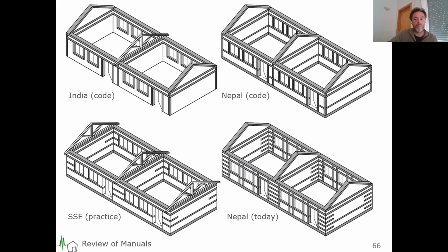So this is that first copy-paste issue that I've already shown. The second reason is panic, pure panic. There's no other reason why all of a sudden someone tries to cram in as many bands and poles and posts and whatever in such a small building. The thing is that, first of all, you wonder why, because even the Nepalese building code doesn't require it. Second of all, we know that in these little bits of masonry, you get concentration of forces that you really don't want. So that's one thing. There's research from IIT Kanpur that shows that.